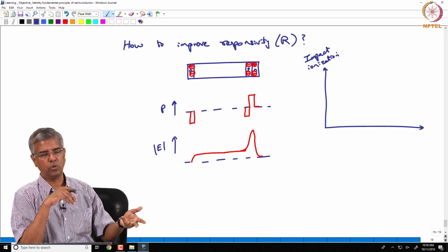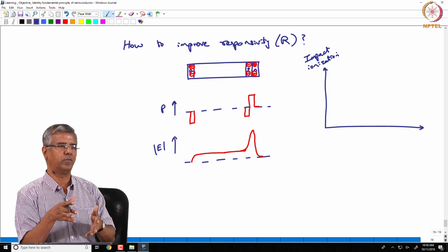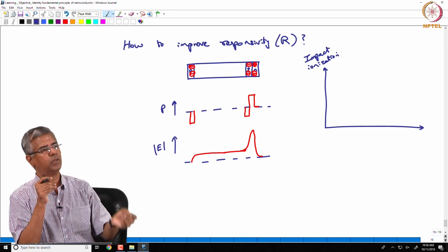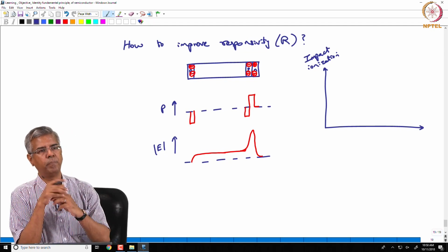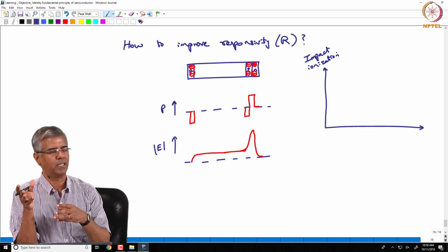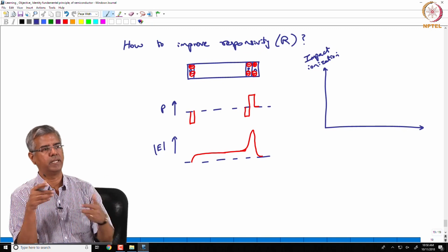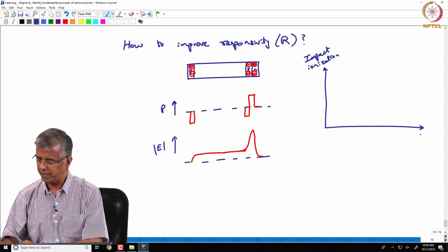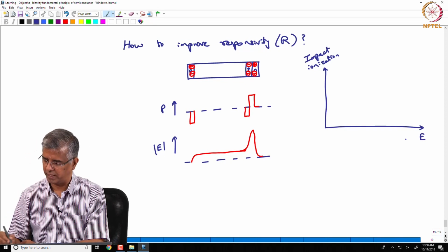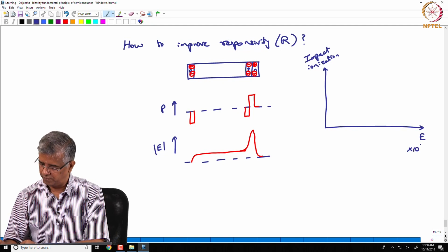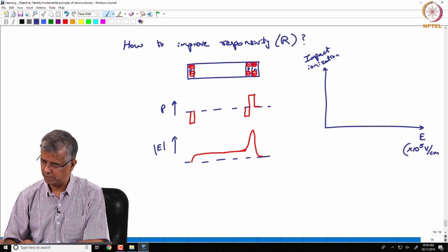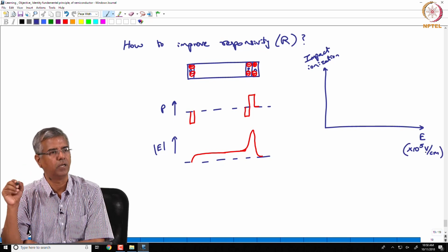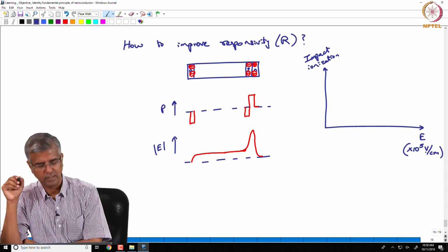And those electron hole pairs still carry a lot of this momentum. So those can go and create an impact ionization on the neighboring atom and so on. So this entire process can multiply. And if you look at the impact ionization as a function of the electric field, we are tracking electric fields in the order of 10 power 5 volt per centimeter, very close to the breakdown strength of the material.